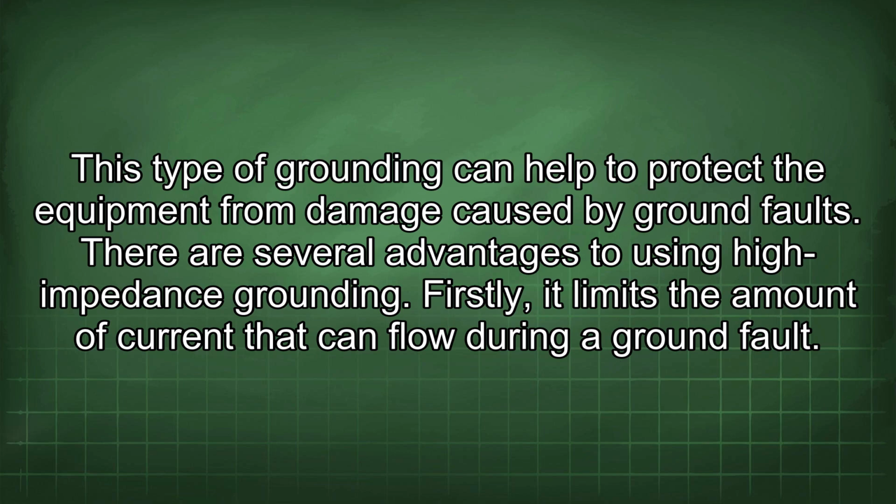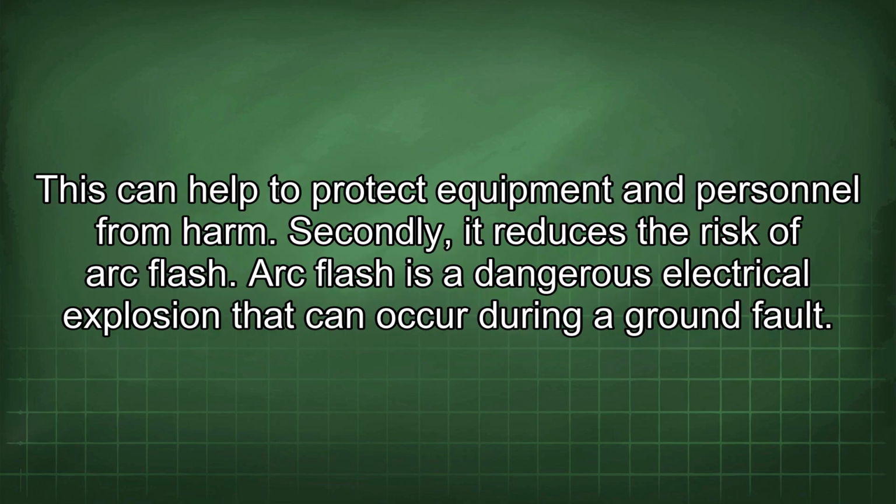This type of grounding can help to protect the equipment from damage caused by ground faults. There are several advantages to using high-impedance grounding. Firstly, it limits the amount of current that can flow during a ground fault. This can help to protect equipment and personnel from harm.